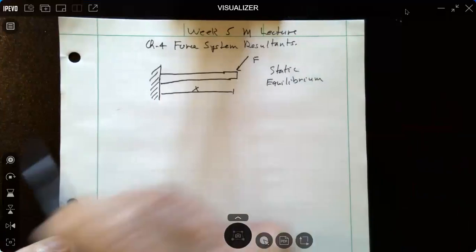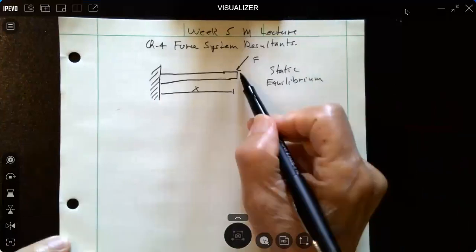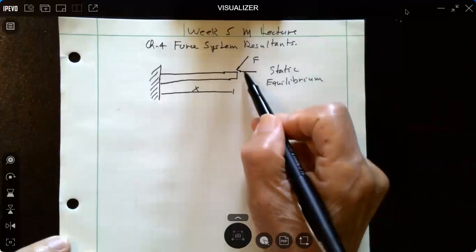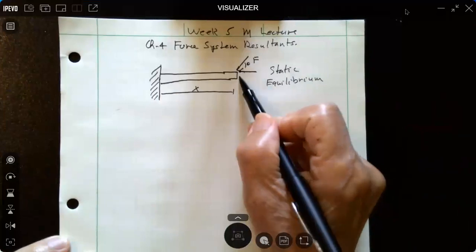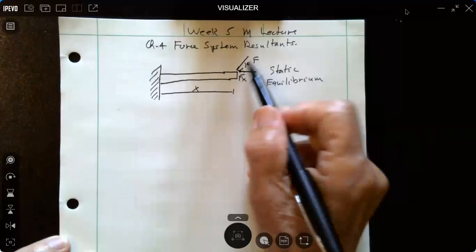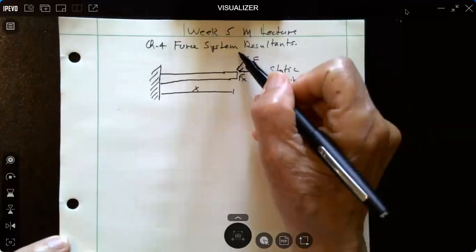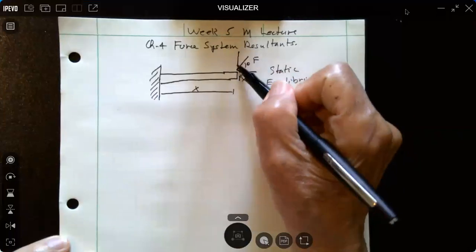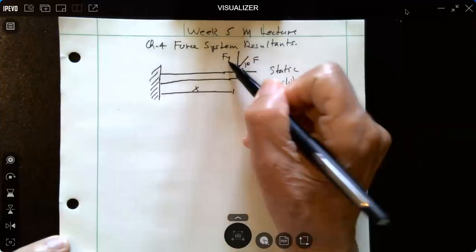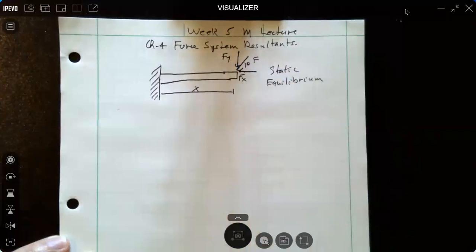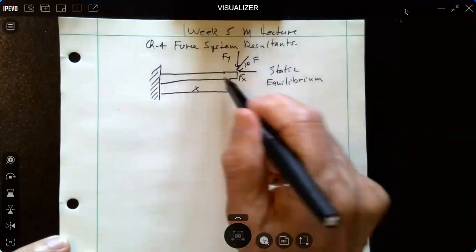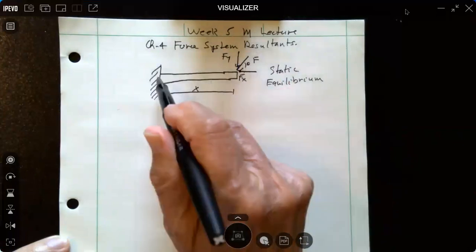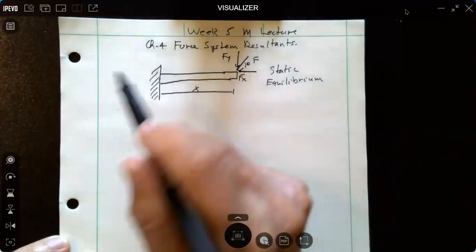We're going to talk about components also. If I have, and this will be given some angle theta, we have a force in the x direction from this force at an angle theta, and there's a force in the y direction. Okay, so we have 2 forces acting at that point. The question is, for this to be in static equilibrium, what has to happen at this support?